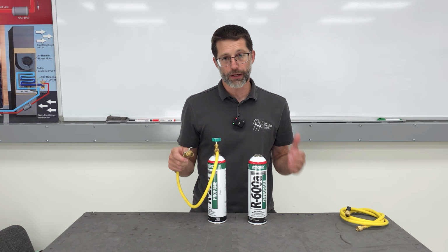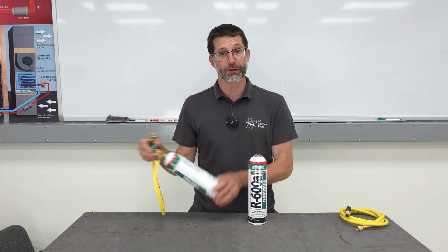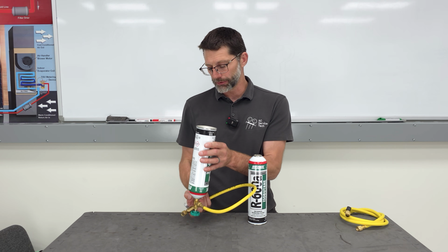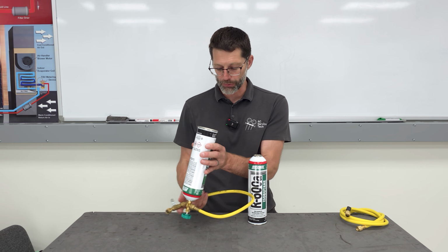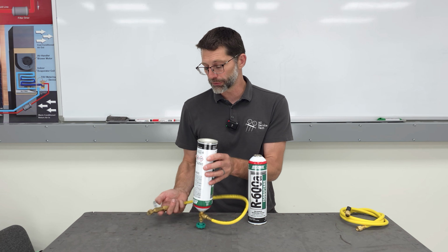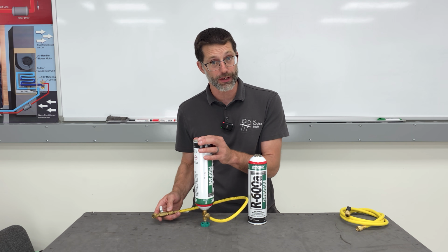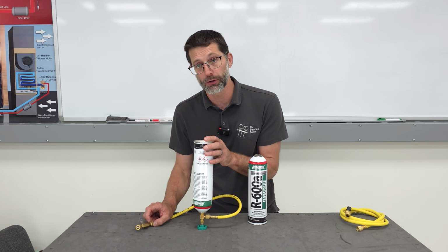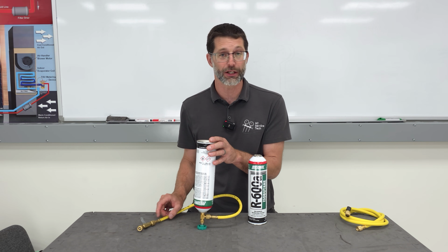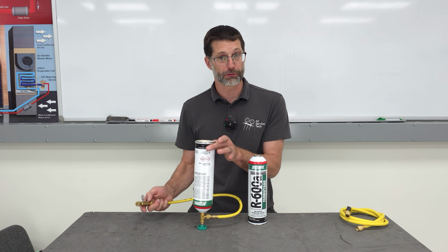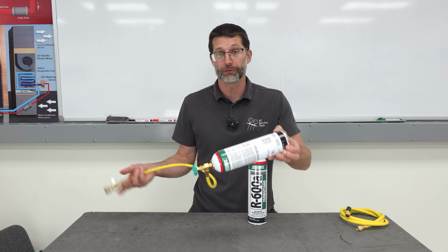If you want liquid in the hose, you would need to flip this upside down, and then open the bottle right here, and purge any air out of the hose so you have liquid refrigerant right at the end here before you set this on the scale. And you'd need to isolate the hose to make sure that it doesn't move and change the weight on the scale before you break that vacuum with the exact amount of refrigerant needed, which may only be a few ounces, and that's it.